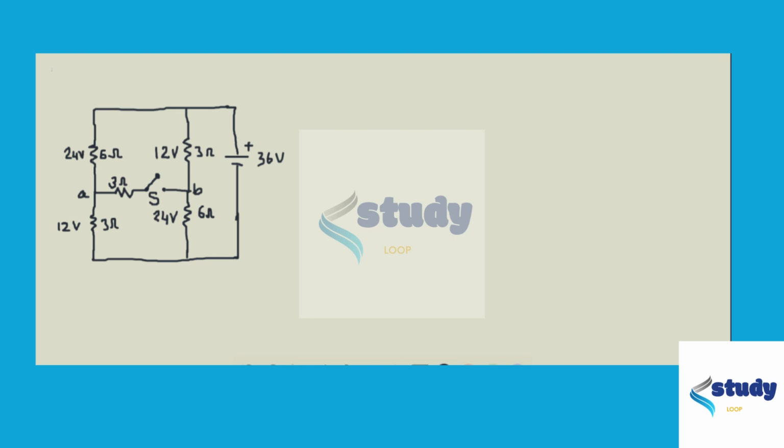Now if you look in the figure, this point here has 36 volts and 12 volts in between, so point B should be at a potential of 24 volts. Similarly, point A should be at a potential of 12 volts, because 36 minus 24 is 12: this point has 36 volts and in between 24 volts is dropped.